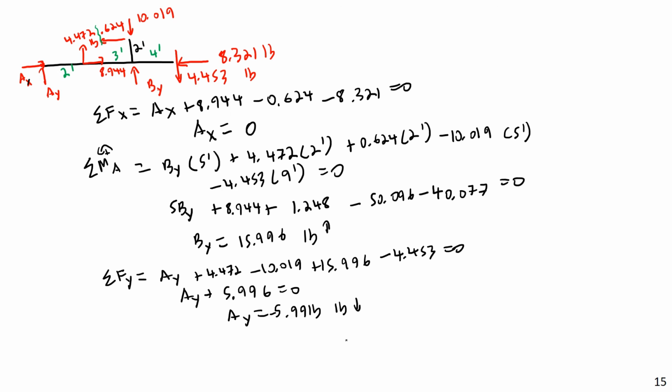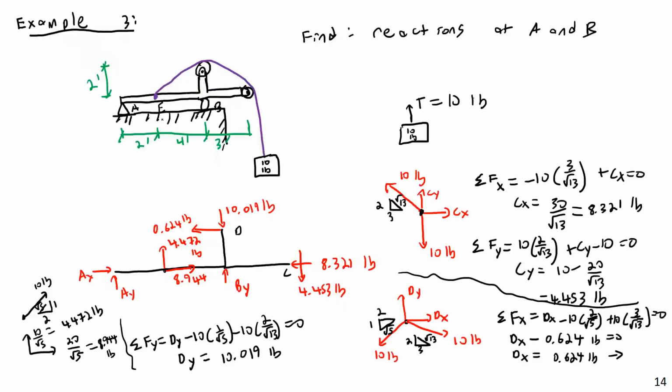Now, I did want to mention there's something really interesting here. Notice the actual AX is 0. In other words, this doesn't need any horizontal force to actually hold it in place. And the reason for that is that we have what are effectively internal forces here.